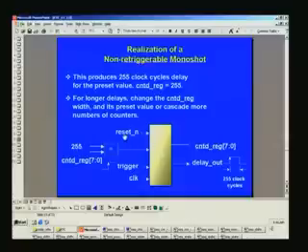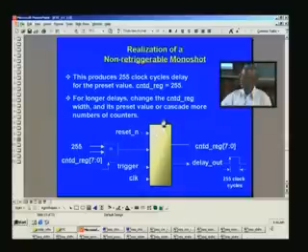So here is a reset once again, because this is based on a counter, and that counter we call counter D here. D stands for delay, and the output is delay out. You get 2 clock cycles as such, and if you require, you can also see what the present value of the counter is, otherwise use it internally.